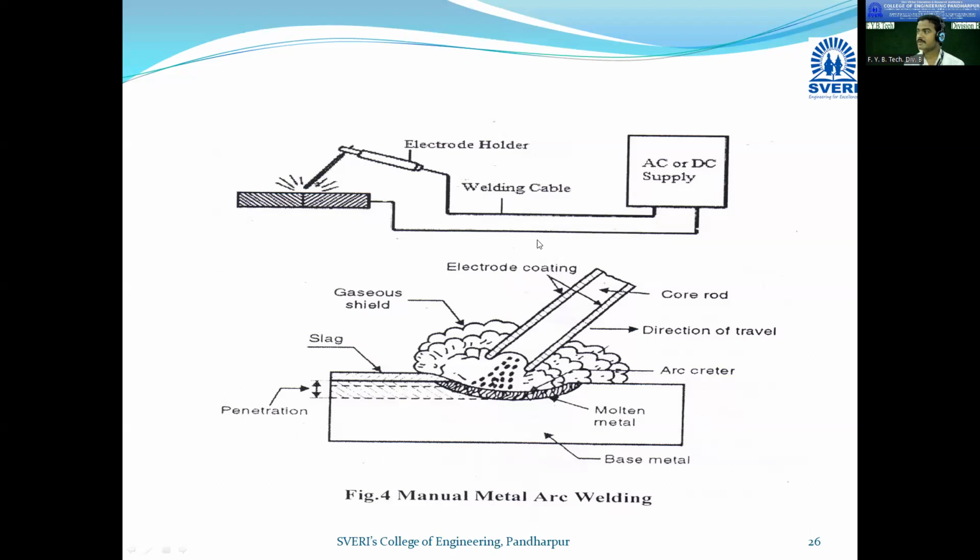Now question may be in your mind. So for carrying out the welding process, what is the range of temperature? आता तुम्ही heating करताय. By using welding rod, you are taking the welding rod nearer to the metal piece and we are producing arc and heating will be carried out. So temperature will reach around 4000 degrees Celsius maximum. म्हणजे प्लेटची thickness त्याच्यानुसार आपण करंट व्हॅरी करू शकतो. Okay.